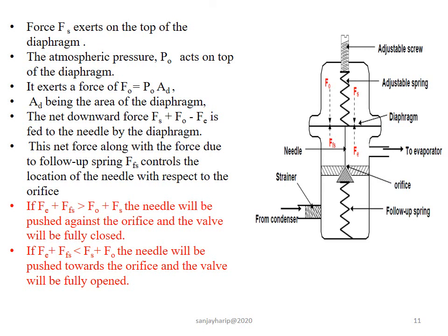If the evaporator pressure plus spring pressure is less than the Fs plus Fo, the needle will be pushed against the orifice and the valve will be fully closed.